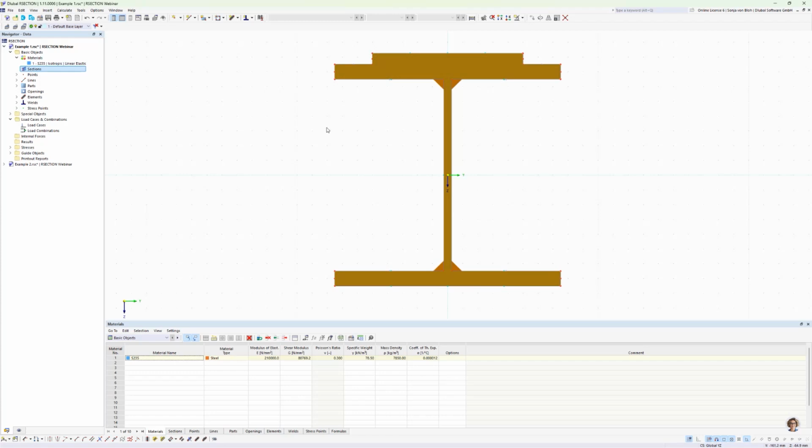The connection between the flange and the reinforcement is made via a lap fillet weld. This type of weld provides a direct connection between both components, making additional connection elements unnecessary. Lap fillet welds are suitable for elements that run parallel to each other and make contact at least one point.